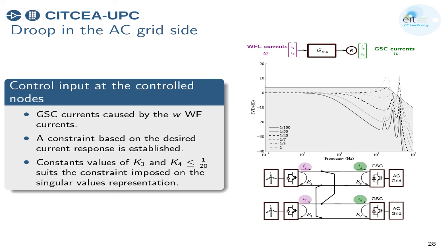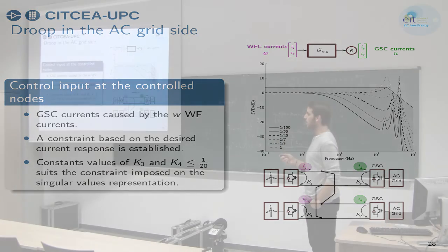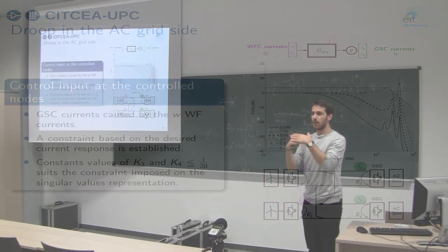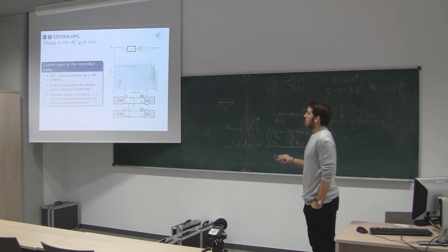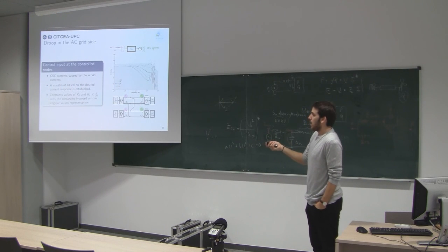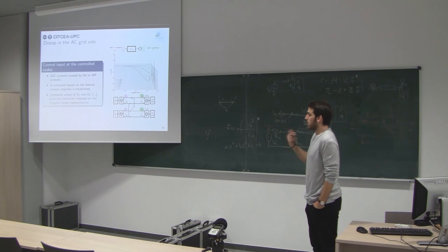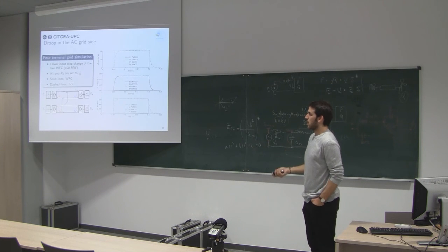So between those two, the error defines a maximum value of droop, and the current defines a minimum value of droop. No, on the other hand, the current defines the maximum and the error defines the minimum. So in that way we can operate the converter in that area. Okay, so based on that, I selected 2 different constants in that range, both set to the same value, and I did some simulations.